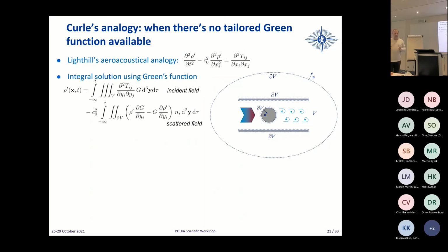That's something that you get from an LES or experimental data. It's something that is generally not infinitely accurate. Now derive something that is contaminated by noise, and you go for failure typically, because this emphasizes the contribution of noise compared to your signal. So to derive something you don't know is generally a bad idea.